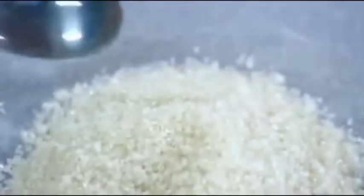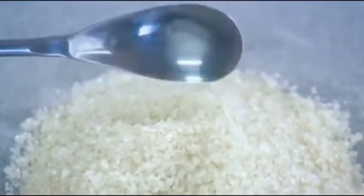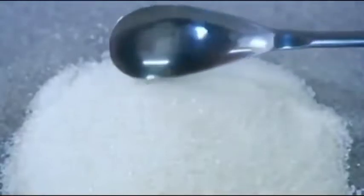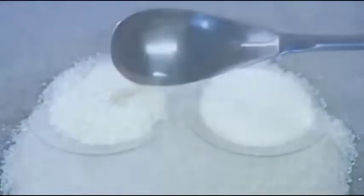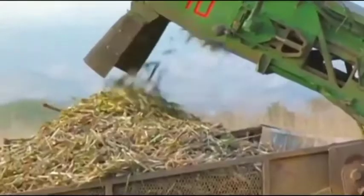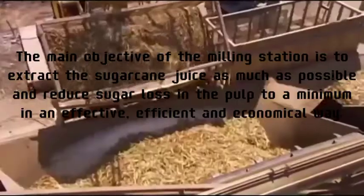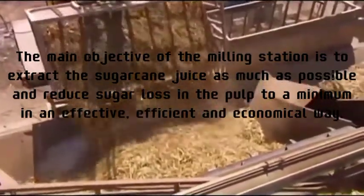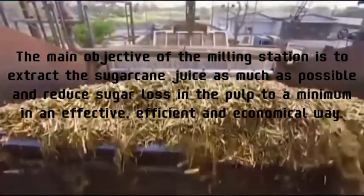I will explain about the sugar industry, tools and the sugar factory. The milling station. The milling station is a very important station because it is the earliest process in processing sugarcane into sugar. The main objective of the milling station is to extract the sugarcane juice as much as possible and reduce sugar loss in the pulp to a minimum in an effective, efficient, and economical way.